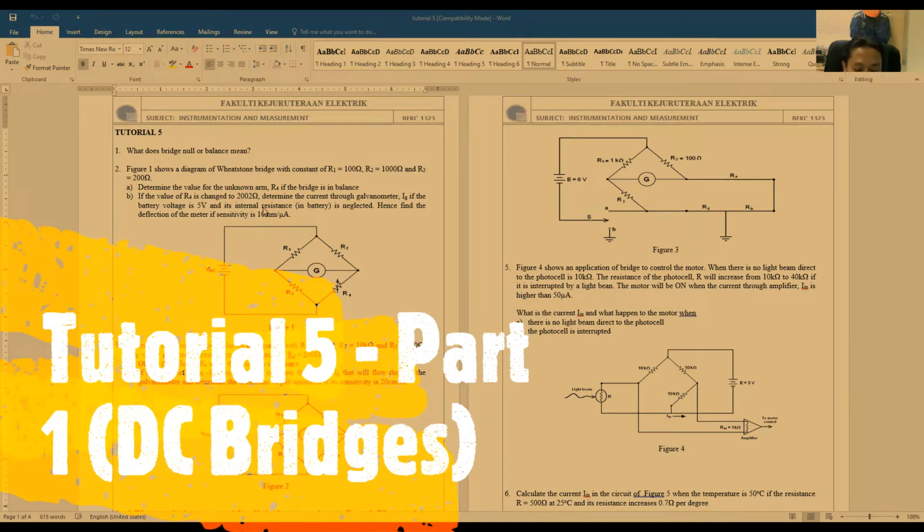So question number 1: what does bridge null or balance mean? This one is theoretical. You can get it from the notes or from Google. From the notes, the bridge is said to be at balance when there is no potential difference between the meter, or no detector. So no current flows through the meter. That is what we call the bridge balance.